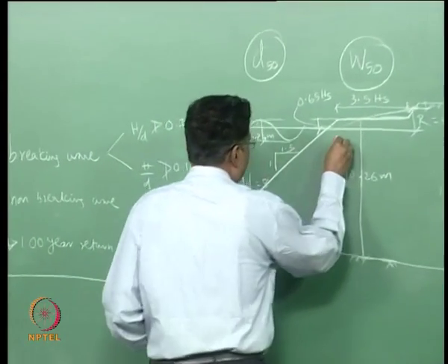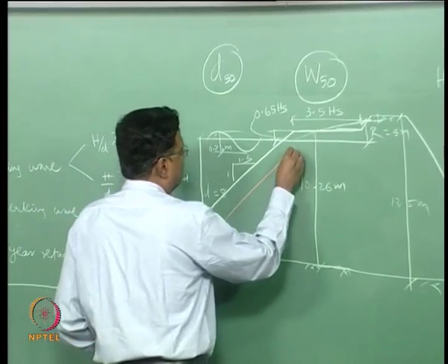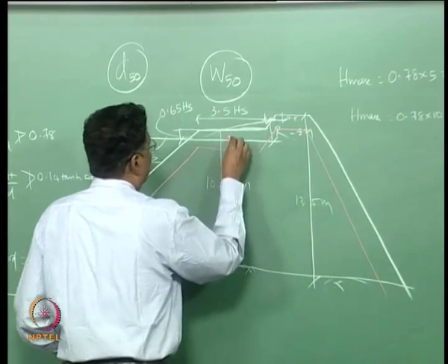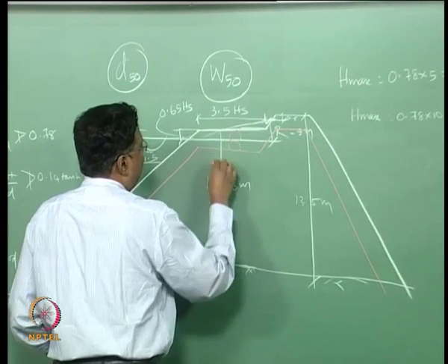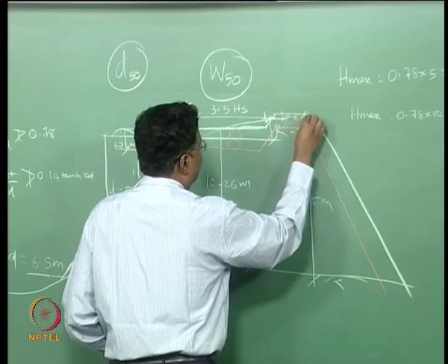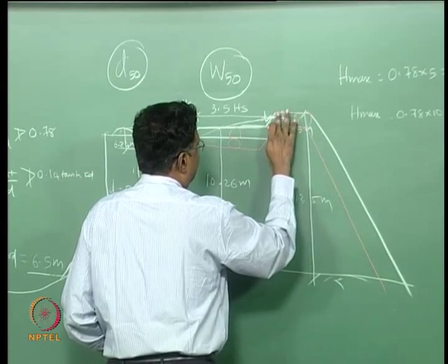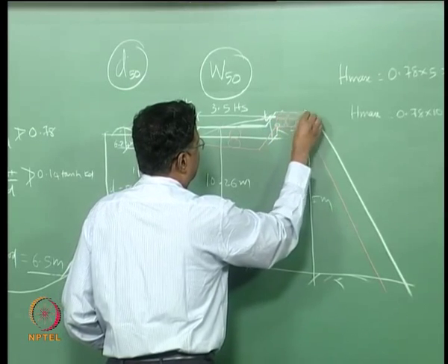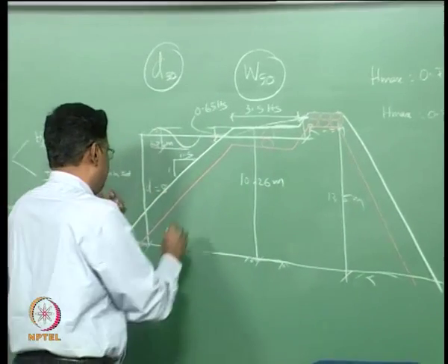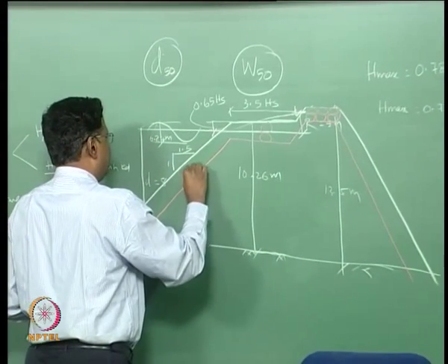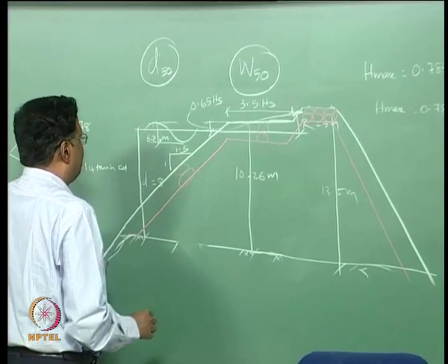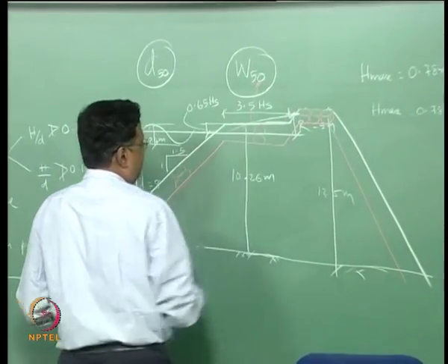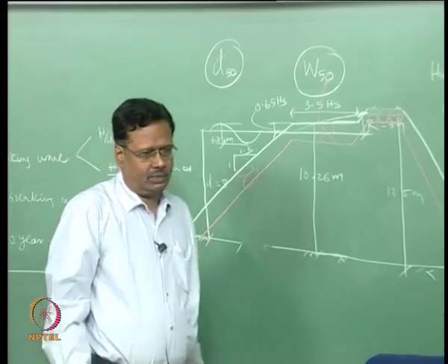So now what we are designing is the armor. I have told you that you should have at least 2 layers here, and you should have at least 3 here. It will not be exactly like this, but with some odd shapes it is preferable to keep this. The stone we are using here is W50, that weight is about 6 tons.